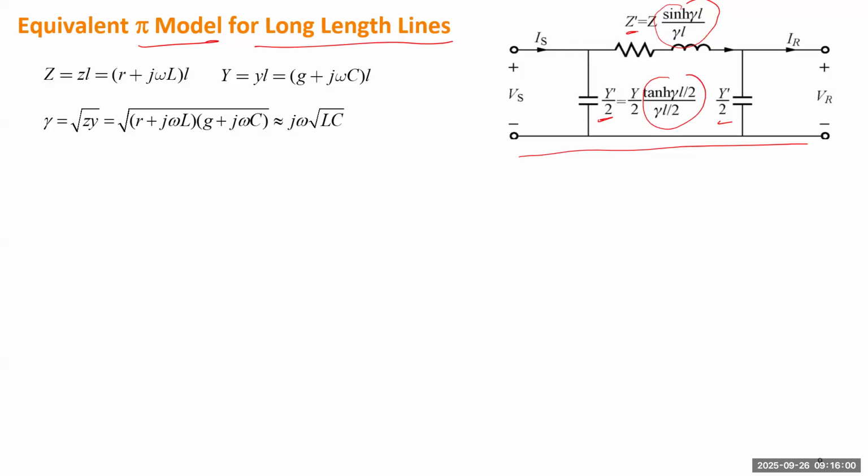So that would be very convenient, especially when you study a large power system. There could be many short lines, many medium lines, many long lines. So taking the same structure for the line model, which could be a pi model, is very convenient. You can just organize the data sheets with the series impedance, including the real part, the resistance, the reactance because of the inductance of the line, and also half of the total admittance to the ground. We put the two halves on two ends.